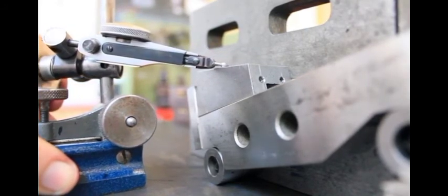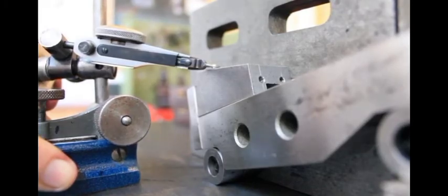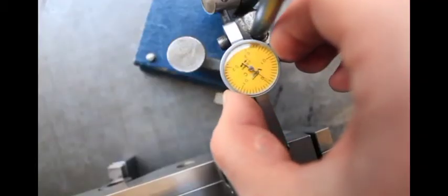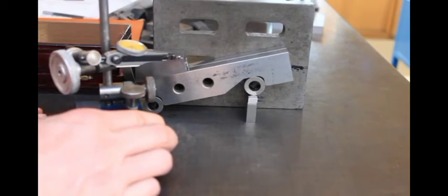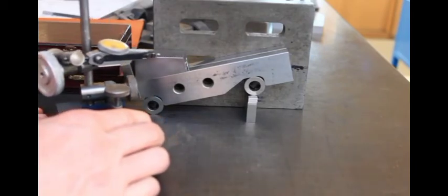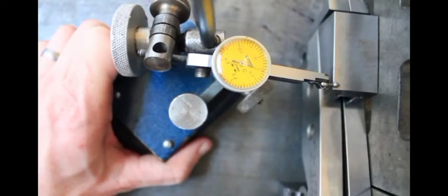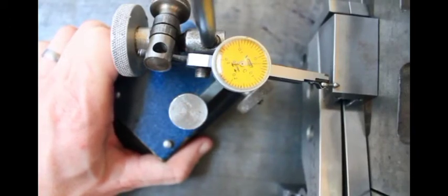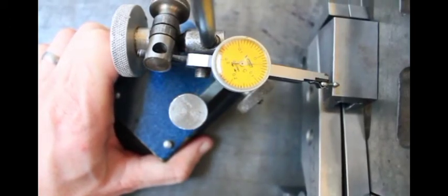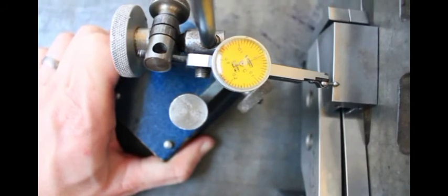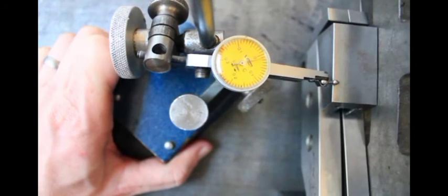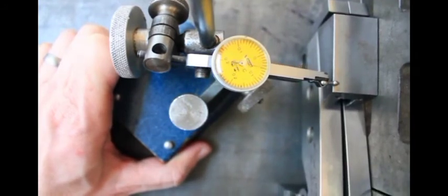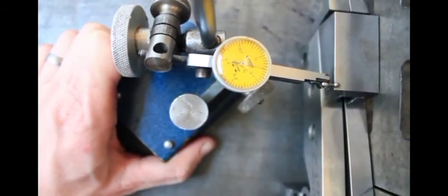Once we're happy that it's in correct contact, we can zero out the gauge for a setting, run it back and forth once again, and make adjustments to the slip gauges on the right hand side so that it does actually run flat and true. So here we can see it's actually raising a little bit, so it's probably a little bit low at the bottom there, so we need to add slip gauges to reduce that error.